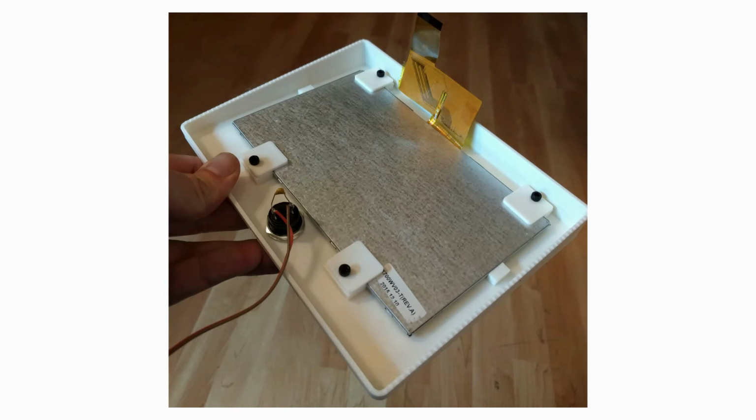And then you can use all sorts of things. It's very flexible about what it accepts. We have 50 FPS because if you work out the dot clock, it works out to about 50 megahertz, 49 point something. But it works fine at 50. It works at anything. It's not very picky. Every time you give it a pixel, it just updates it. You need to do it fast enough that you don't lose the image, but it takes several seconds for the image to fade, so you're not in a hurry. You could go at it pretty low.